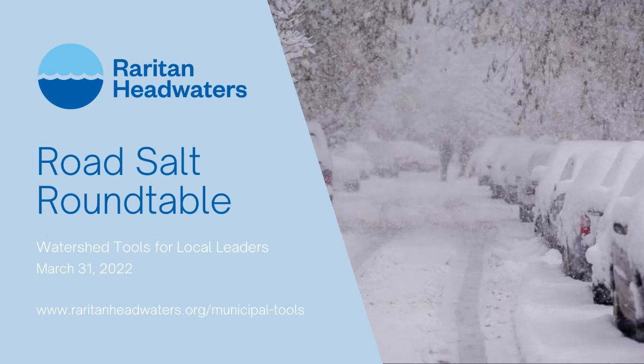One of the benefits that was supposed to occur is, first of all, the liquid jumpstarts the salt and helps it go into liquid form quicker. But the other benefit is that the liquid was supposed to keep the solid material on the pavement longer, so less salt could be used. I've just never seen that happen. Just about everybody's pre-wetting, but I don't see any real reduction in the amount of chemical used. Someone putting down 300 pounds per lane mile is now pre-wetting with calcium or magnesium, and I don't see them dropping the salt application by 30% or whatever the number is that you're supposed to realize. That's right, because they're not measuring and analyzing, which is one of the reasons.